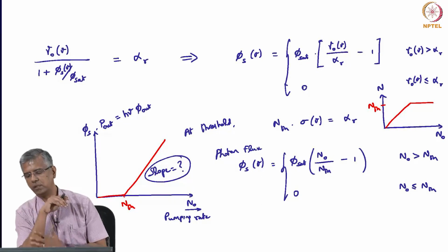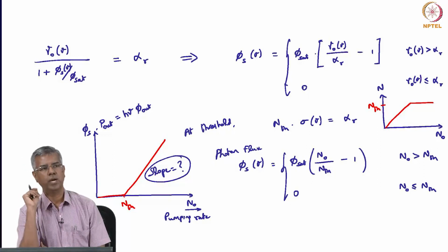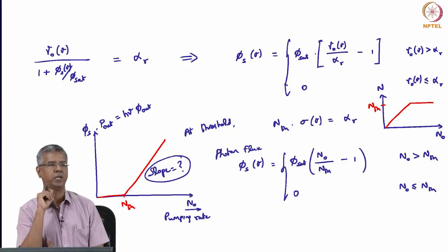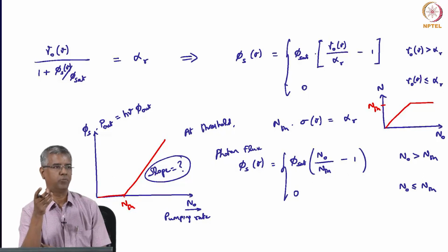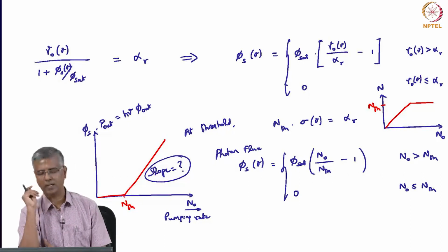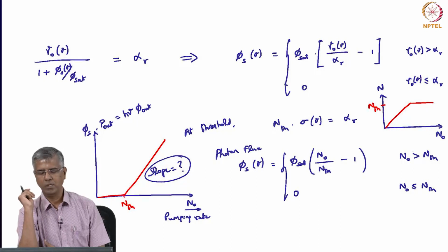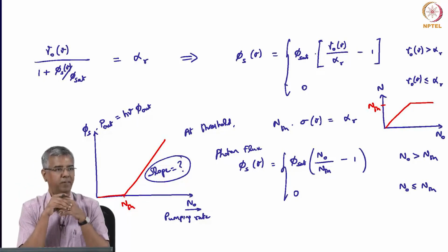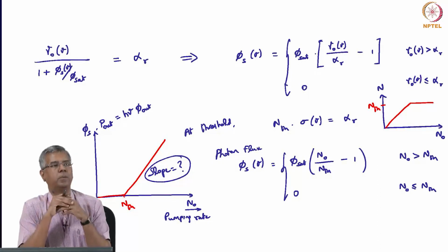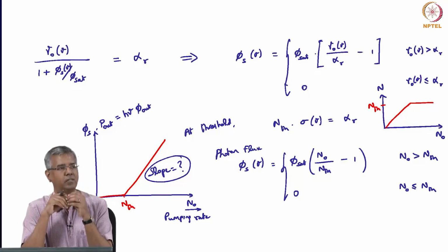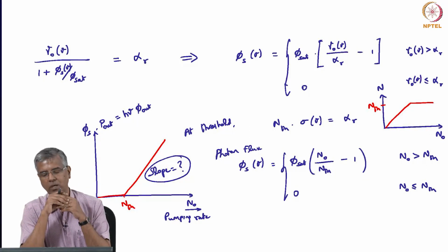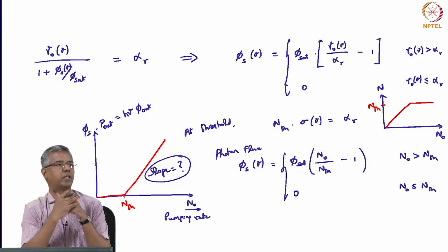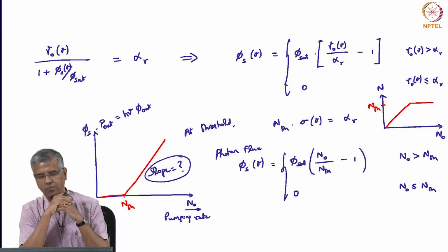So, it is a good question. The question is, do you have only the signal photons coming out, or can you actually have pump photons also come out, right. Any unutilized pump photons can also come out of the laser, and if you have designed your laser cavity well, you would have absorbed all your pump photons, but if the design is not so good, then you have the possibility of those pump photons also coming out, and then you would have to have an external filter at the output to cut off the pump photons.